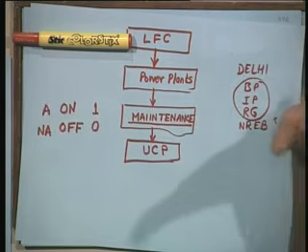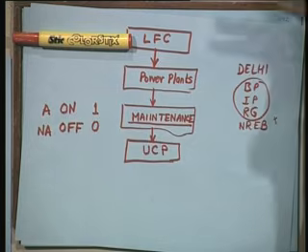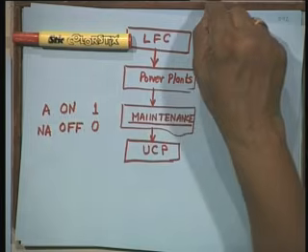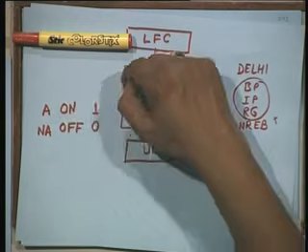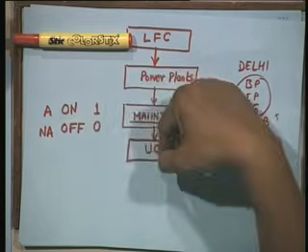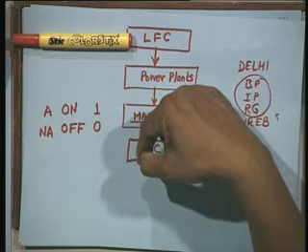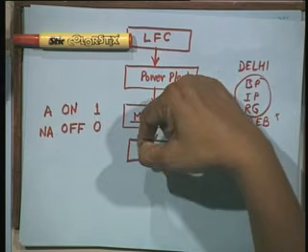Just because you have 20 units in Badarpur, Indraprastha and Rajghat, that doesn't mean you should ask all 20 units to generate power. You may not need it. So the unit commitment problem tells you for a given load which units will be on and which units should be off. How it tells you, that's the solution of the unit commitment problem. I am not going to discuss it today. I will discuss it when the time comes.